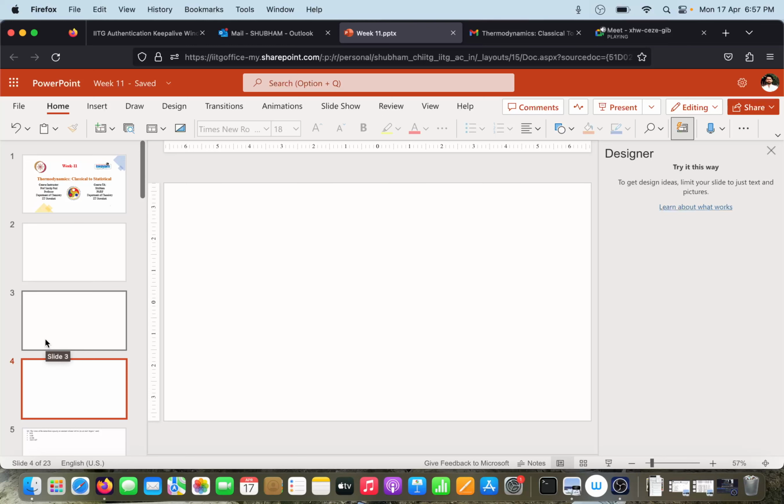2 remaining. So if we are not working on these lines, then the degree of freedom will be 2. And this is the triple point, so here the degree of freedom is 0, and anywhere on this line the degree of freedom is 1. So the answer is 2 at point 1 and 1 at point 2 and 0 at point 3. This is a 2 component phase diagram.